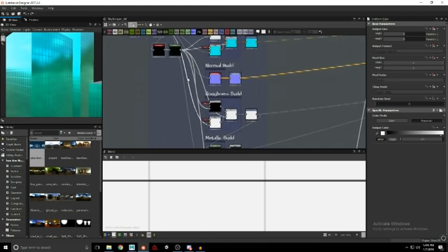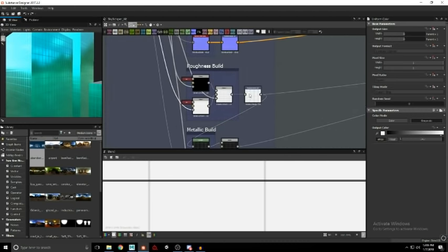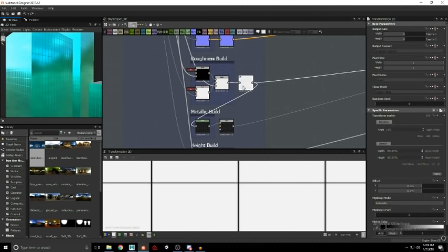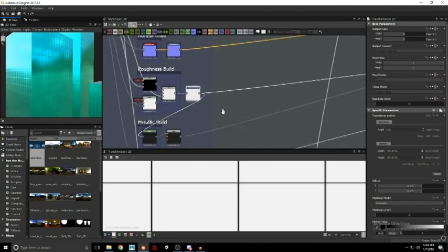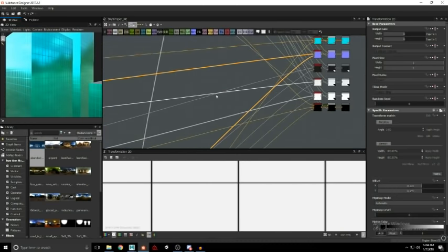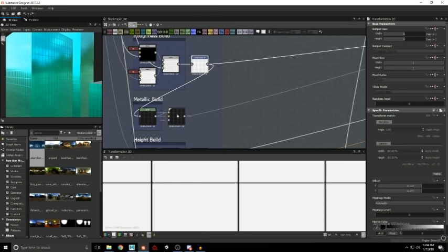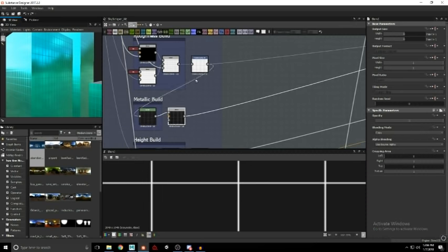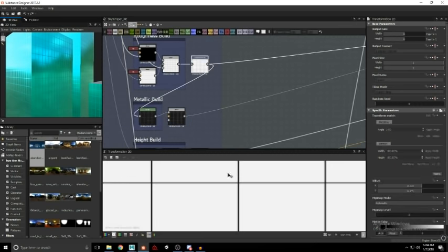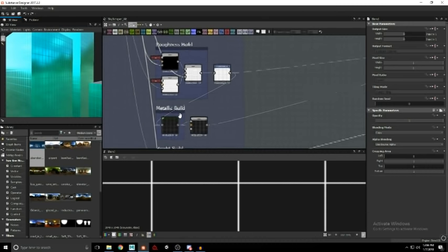All right. And then we're going to get this, and this guy is white color. And over here, he's pulling from this mask up here. If you notice, this goes off to the transform to get the area scale, and then I said, okay, I'm going to go down here and do this. But you notice that this goes off and this goes off. I actually changed my mind. They swap. They cross the streams right here. So this actually becomes our metallic, and this becomes our roughness, because that makes more sense. We want very, very metallic here, not very here. And then this, we want extremely rough here and not very rough here. So just kind of flip-flop these labels.